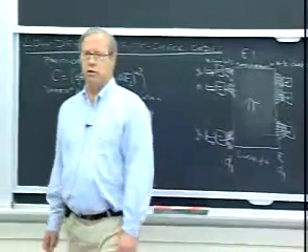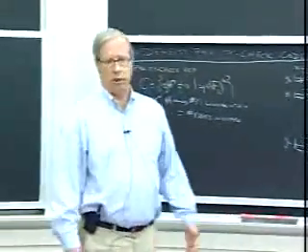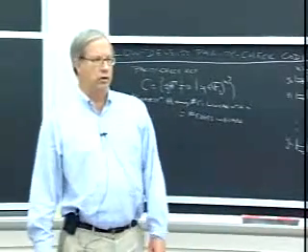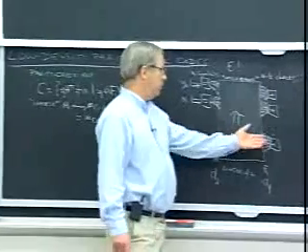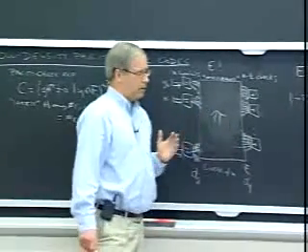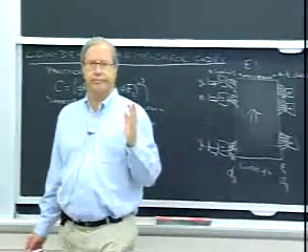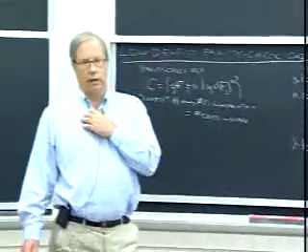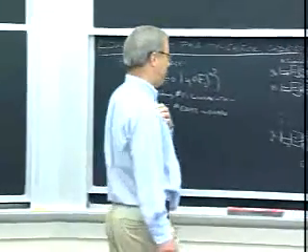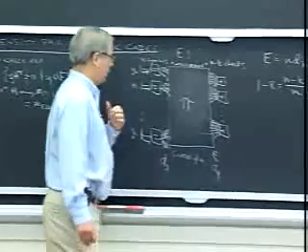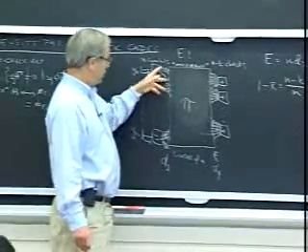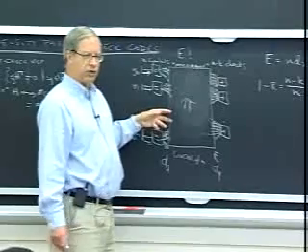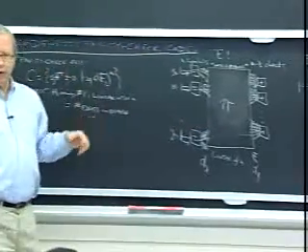In low-density parity check codes, you can do this typically 100 times, 200 times. It's a very simple calculation. You can do it a lot. So you do that. When do you stop? A very popular stopping rule is to stop as soon as, if you made hard decisions on the basis of all these messages, that would give you binary values.